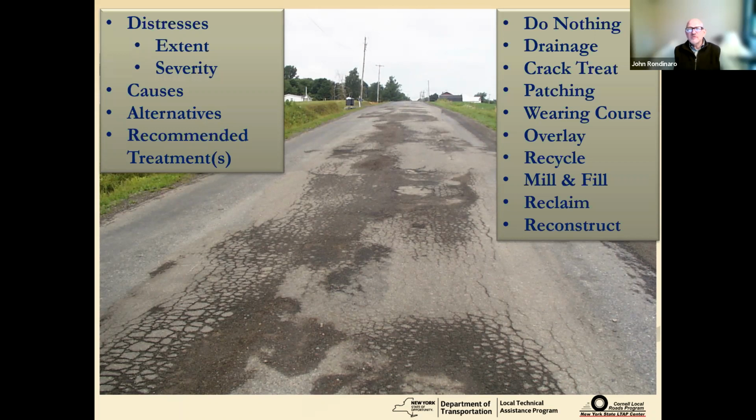Drainage is always something you've got to look hard at. Then in terms of the pavement treatments themselves, in this case, crack treatment, the pavement's way too far gone. The same with patching, you'd have to patch the entire section of pavement. And a wearing course is not going to work here either. The pavement's just too far deteriorated.